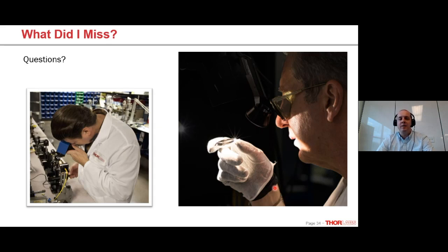And then beyond that, we also need to make sure that our roughness is very low on the surfaces. This minimizes the scatter that we'd see at the surface, either occurring uniformly across that surface or introduced by imperfections like scratches and digs. In those situations, we're looking to minimize that so that we have a nearly pure specular beam that's either reflected or transmitted from those surfaces.